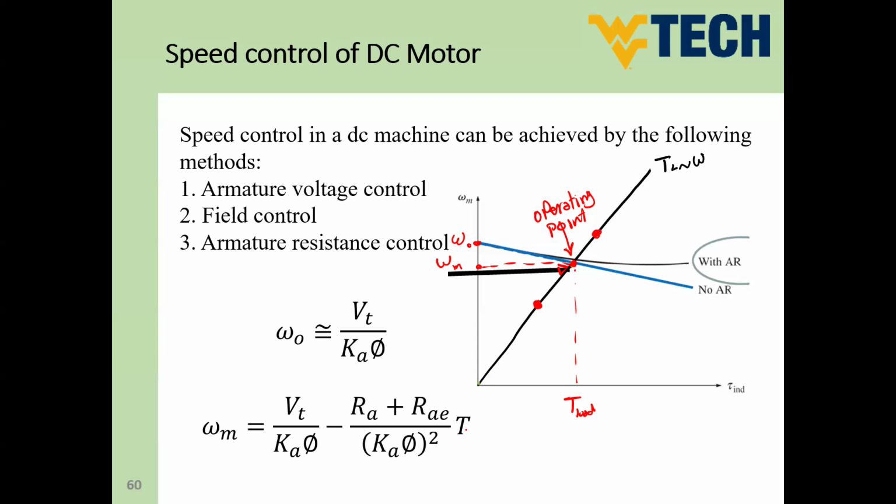So what are the independent variables or parameters that we can use to control this curve? Actually, the controlling parameters are any other parameter in the equation. We have the voltage. We can have the armature resistance, but the armature resistance itself is not a controlled resistance. It's a fixed resistance. However, we can add a series resistance with the armature resistance. So this is the rheostat: a controlled series resistance with the armature resistance in order to control these variables.